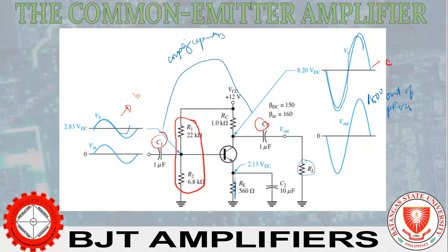So, it indicates that if the base current increases, kung tumaas si IB natin, so the collector current increases, so yung ating IC ay tataas din kasi nga directly proportional si IB and si IC by beta natin. Yung beta natin yung kanyang proportionality constant. So, it's also increasing from the Q point value natin.